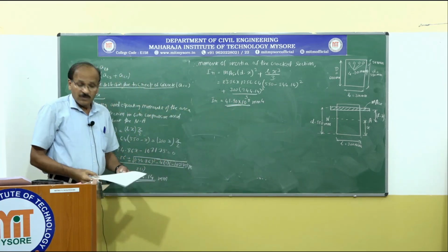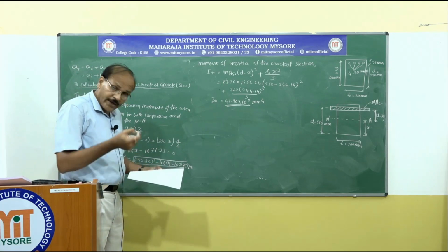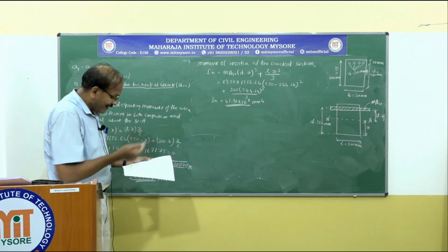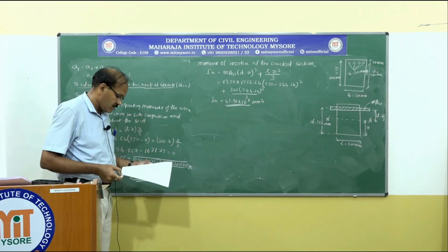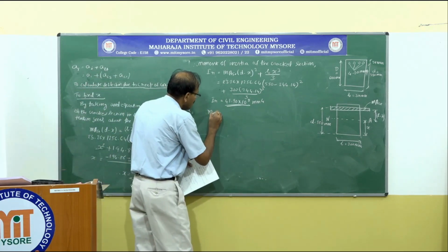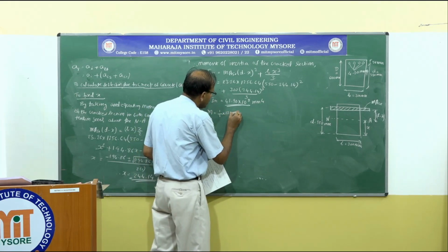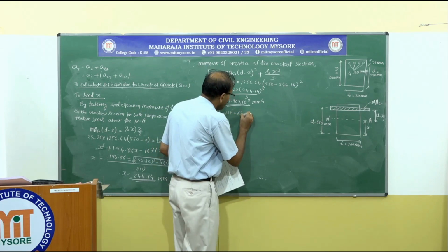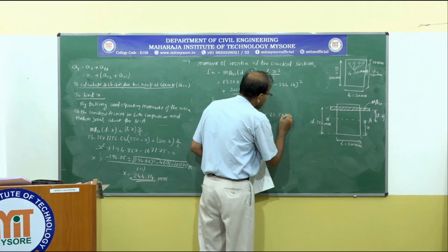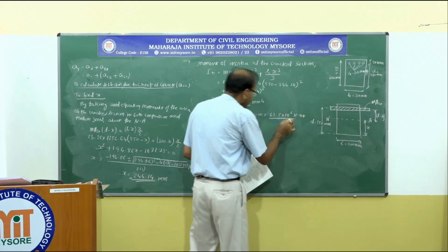Okay. So again, in the equation Ieffective equal to Icr divided by etc., in this we calculated what is Icr. So what else do we need to calculate? M is half the moment, that is half of 125 kilonewton meter, that is equal to 62.5 kilonewton meter, that is equal to 62.5 multiplied by 10 to the power of 6 Newton millimeter. Okay.